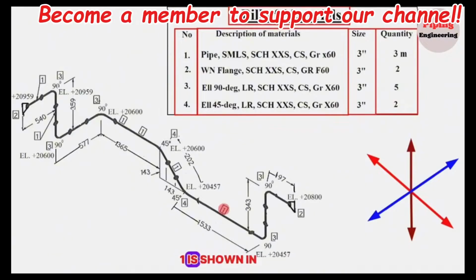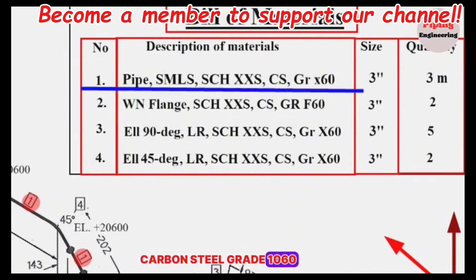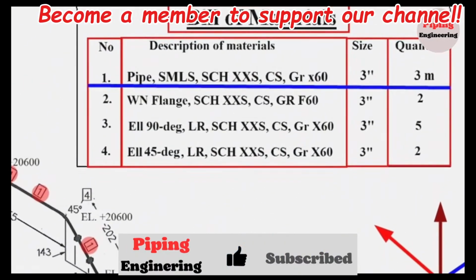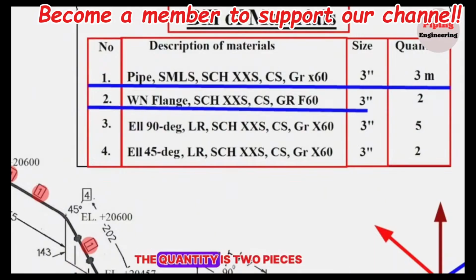Now let's learn the name and number of pipe fittings used in this pipeline. Item number 1 is shown in several places on this pipe drawing. Now let's look at the bill of materials table. Item number 1 is pipe, seamless, schedule XXS, carbon steel, grade 1060, size 3 inches, quantity 3 meters. Item number 2 is shown in 2 places on this pipe drawing. Now let's look at the bill of materials table. Item number 2 is weld neck flange, schedule XXS, carbon steel, grade 1060, size 3 inches, quantity 2 pieces.